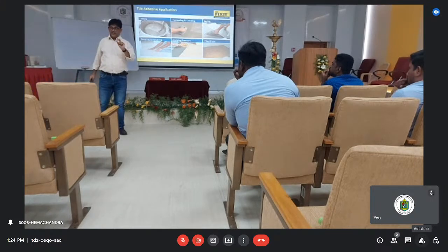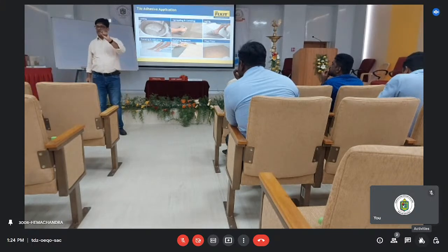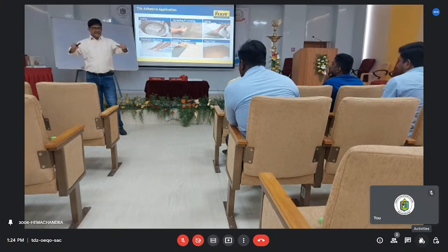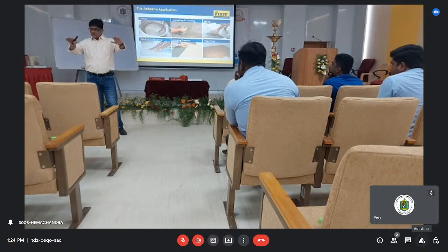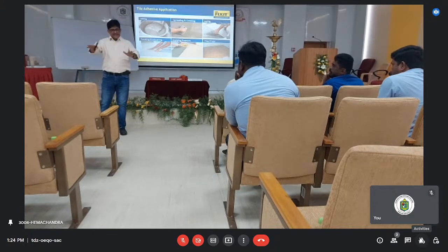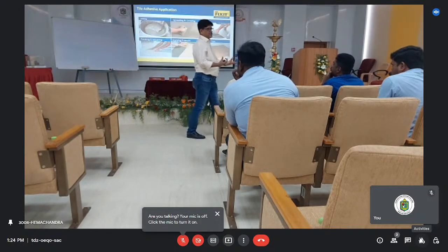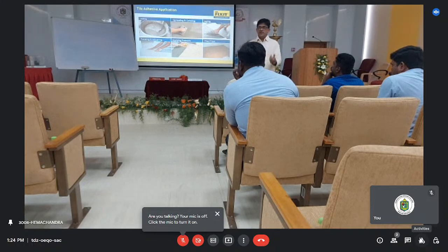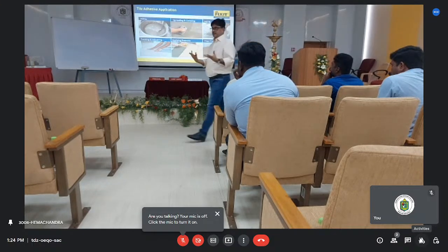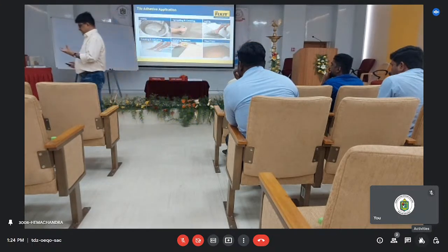After the ridge, depending on what kind of bed you are making, it's going to be 3 mm, 4 mm, 5 mm, depending on that. Then you have to take the tiles, just like you are putting. After putting it, you have to move the tile. The ridge we have created breaks open and it gets bonded. This will ensure the sealing of the tiles. Otherwise, there is a chance the tiles will try to come off. So tile adhesive application is again an application you have to do rightly.